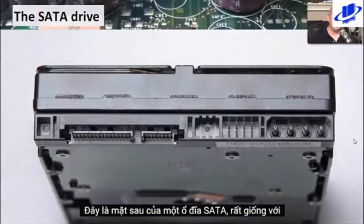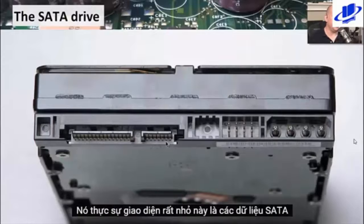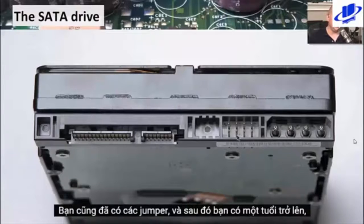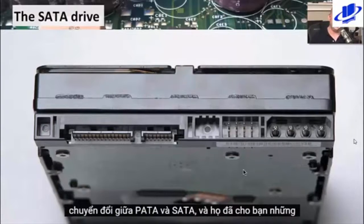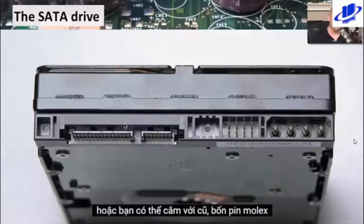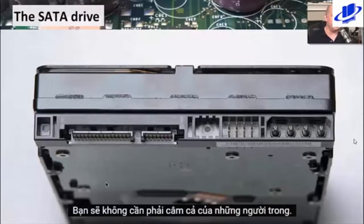This is the back of a SATA drive, very similar to the PATA in that your interfaces are on this side. It's actually this very small interface that is the SATA data connection. This larger interface is actually the power for SATA. You've also got these jumpers, and then you have an older traditional power connection. This drive was built for a computer that may be transitioning between PATA and SATA, and they gave you the option: you could either plug in with the newer SATA power, or you could plug in with the older 4-pin Molex connector onto this drive. You would only choose one of those. You wouldn't need to plug both of those in.